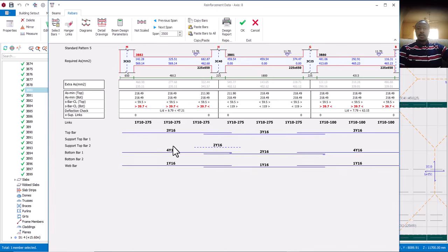Can you see now? Definitely your width of 225 will not be able to contain it. Are we together now? It means that your width of 225 will not be able to contain that 8Y16. It's too much, so the spacing between them is as good as there's no space between them.